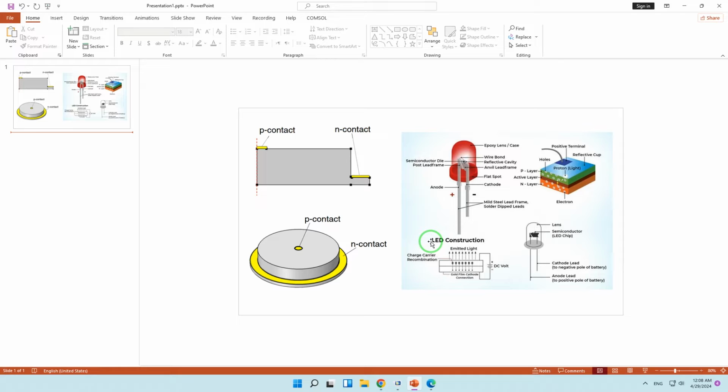In the second study, we use a stationary study where we sweep the applied bias voltage of the device to see the current-voltage curve and also the optical emission characteristics of the LED.